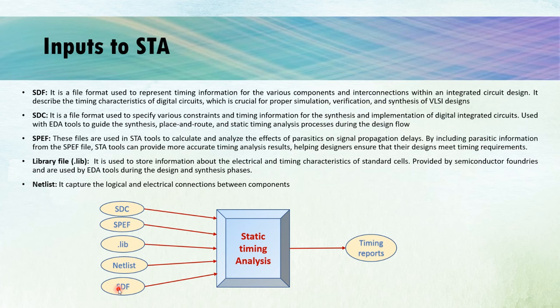The next input to static timing analysis is the SDC file. SDC stands for Synopsys Design Constraints file. It's a file format which is used to specify the various constraints and timing information for the synthesis and implementation of digital integrated circuits. This SDC file is primarily used by the EDA tools to guide the synthesis, place and route, and static timing analysis process throughout the design flow.